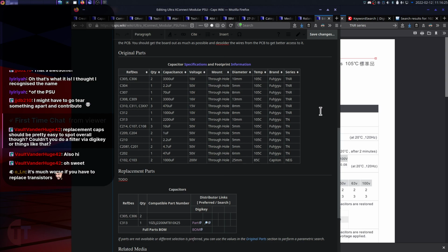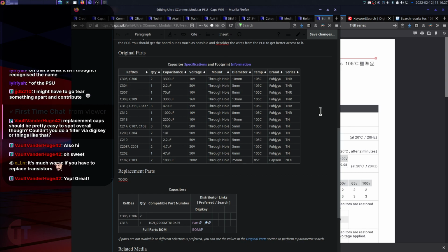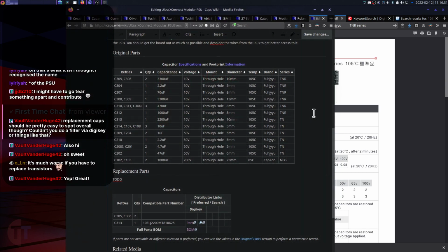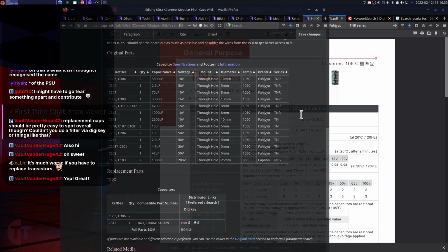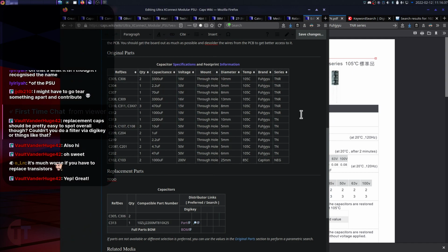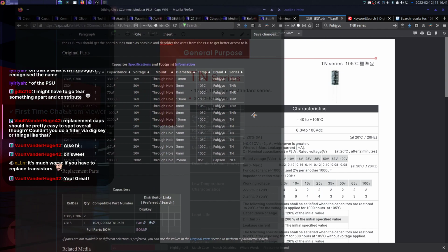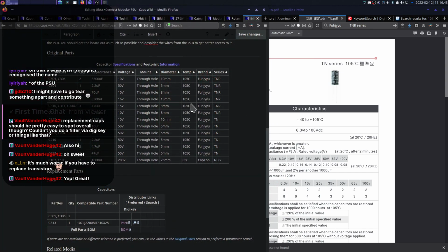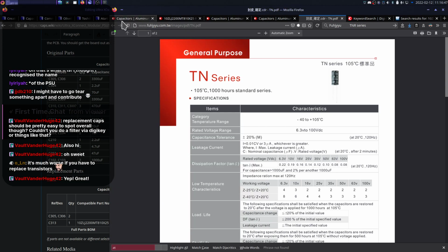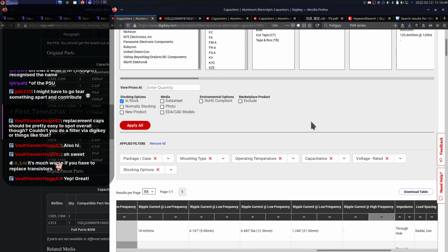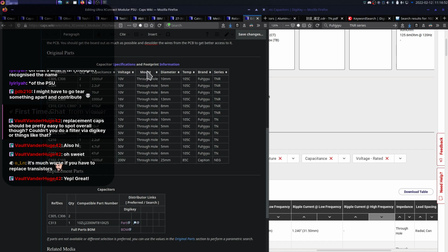Oh man, to me the worst is diodes, because you really can't tell what they are without a schematic. I replaced a Zener diode in a Pioneer SX780, and it was a 14-volt Zener diode. It doesn't say it's 14 volts on it. I was only able to find that out because I had a schematic that listed that it was 14 volts. So to me, diodes are the worst. Hopefully transistors have case markings on them. But all right, let's continue on here.